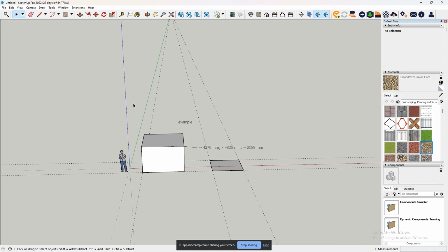Then we have the paint bucket tool. Another quick tip is if you want to highlight certain areas of a model, if you only want to highlight one area, you would highlight a box going left to right like that. However, if you want to highlight the whole area, you want to drag your mouse right to left like this. It does make a difference because left to right only highlights what's in the box. However, right to left highlights anything that the box touches. So you see, even though I'm not highlighting the entire lines here, I'm just touching them and it still counts it.